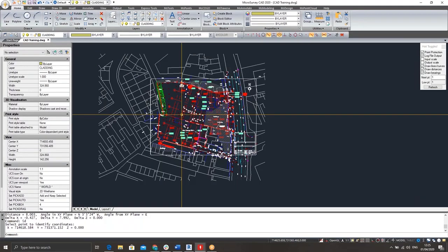Okay, so again, if you're trying to bring in 3D information, whether it's for setting out for roads or you want to input into a machine control, you need to identify first whether your information is in 3D or in fact 2D. The majority of the time, most setting out on sites is in 2D, but again, we just need to understand our drawing and make note of these things prior to bringing them into our field software.